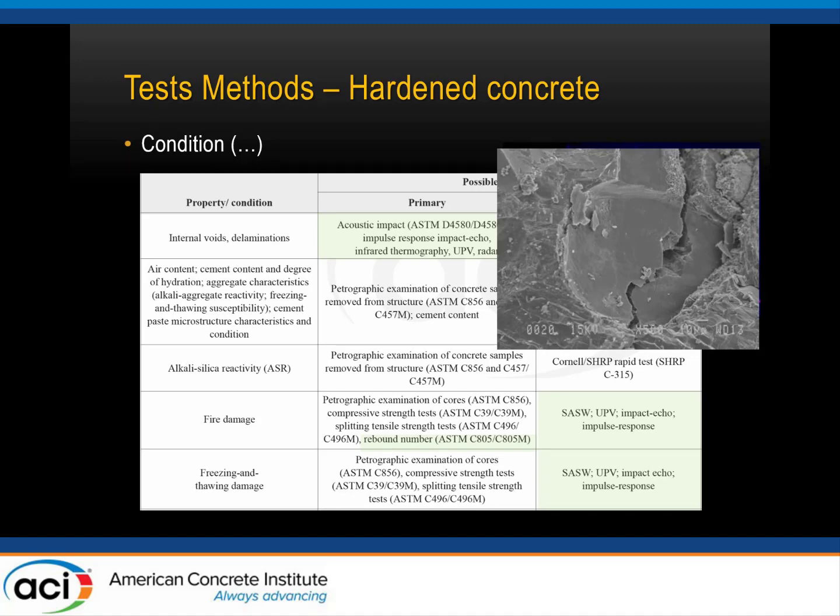And petrographic exams go from the visual exam to SEM through optical microscopy. It uses those different tools in order to assess the different phases, assess the different symptoms in order to confirm different pathologies.